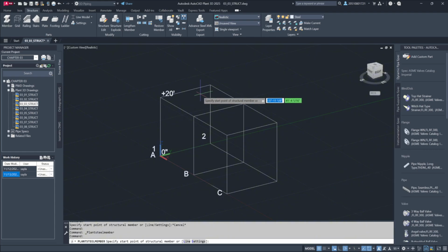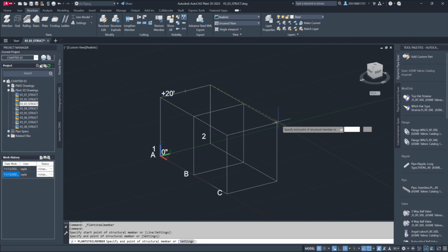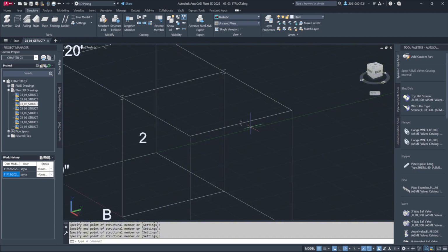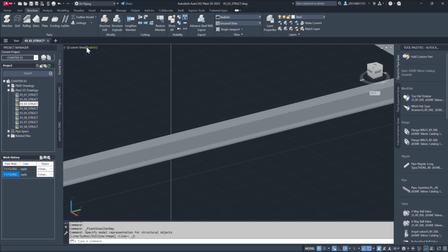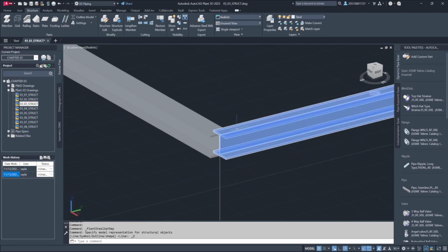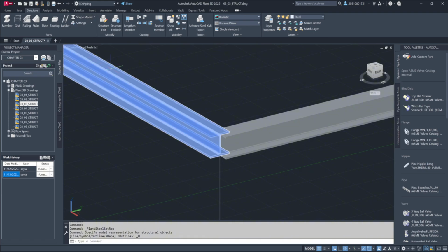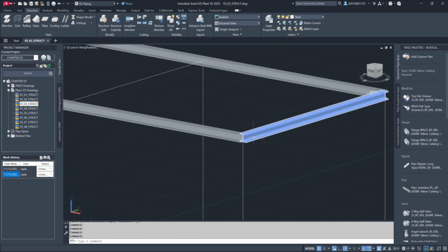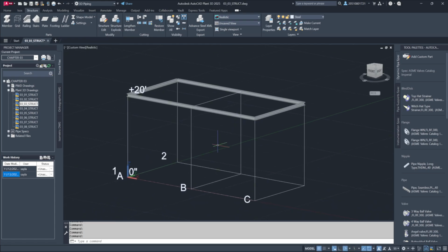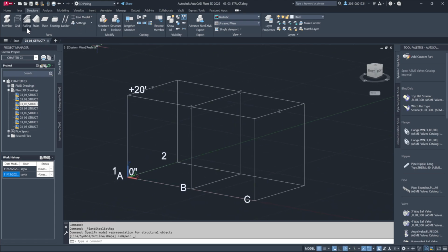points. Now, insert the steel by clicking the member button and adjusting to line model mode for clarity. Select endpoints to mark the placements. Although shapes may not initially be visible, small markers will show they're correctly placed along grid lines, enabling you to display the steel through various modes such as outline model or shape model, each offering different views of the steel structure. While adding beams, stick to the line model to clearly view the grid, facilitating precise snap points.